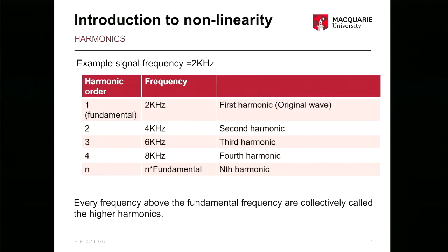If you have 2 kilohertz and you want to generate 4 kilohertz, what would you do? You need to rely on harmonics to generate that. So there are applications. We will look at mixers as one application of using higher harmonics, or modulation or intermodulation. We'll learn about the basics this week, and we will go into mixers in the next 2 weeks.